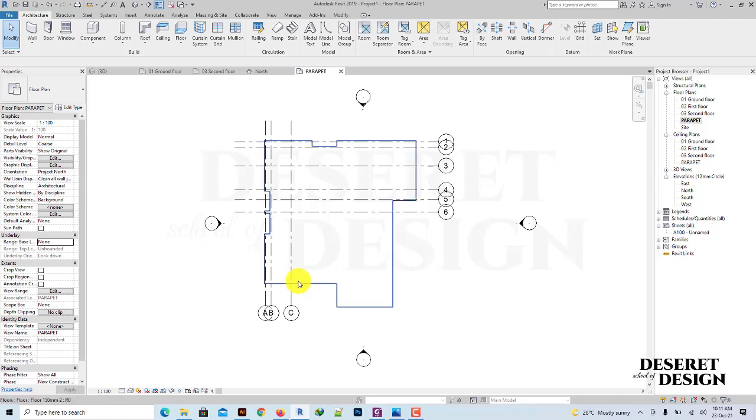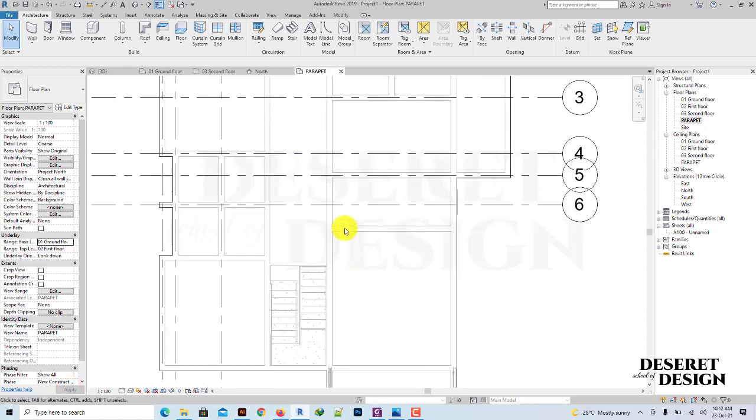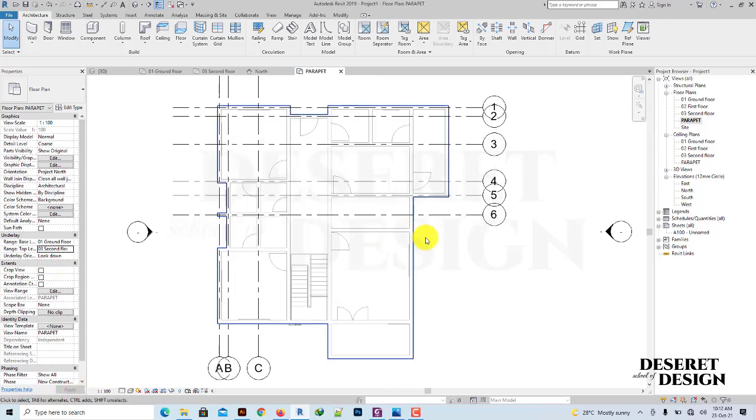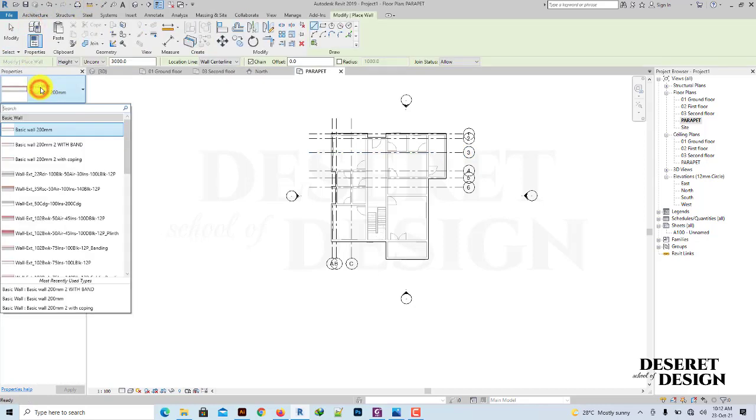So let's say ground floor. Go back to underlay inside my properties. There's underlay here. In here, I'm going to ground floor. Let me apply. Make the ground floor walls an underlay. Are we okay? So here I'll set it to my second floor. I'll say apply. So I want to create my wall, my parapet. So I'll go wall, select what we created, right?